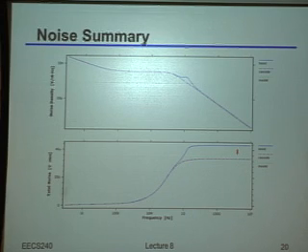Yes? This little hump here? Ah, okay. This turns out to be directly related to my choice for the phase margin of that boosting loop, because it just means there's a little bit of peaking in that boosting loop. You're seeing that show up in the noise behavior as well, but you can see it's a very small effect.